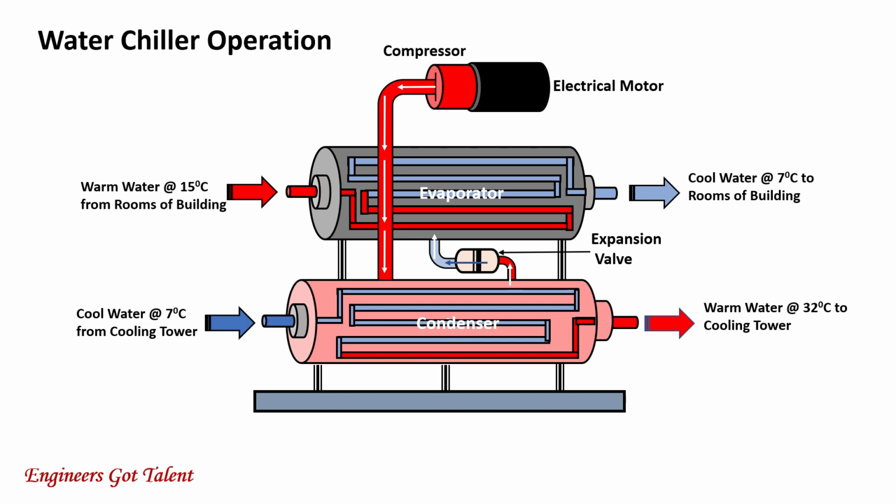It is really low. It doesn't take a lot of energy to boil the refrigerant. The refrigerant exits the evaporator as warm vapor, low pressure. It will then be sucked or drawn by the compressor and the cycle repeats. The warm vapor, low pressure refrigerant will then be compressed back at the compressor.